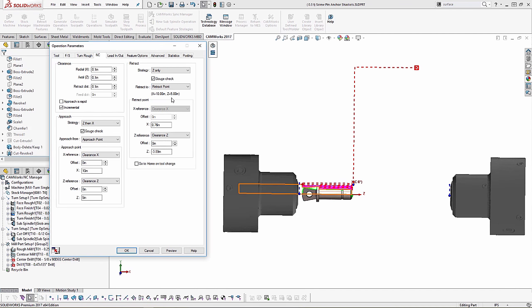And the preset is tied into the machine parameters posting tab. That's similar to what we used in the past. Or we can go to none. And we also have this box, go to home on tool change. Okay, so all of these are a lot of new options. It also includes a gouge check on the retract. This is much improved and it's going to be a very welcome change for current turn and mill turn users.